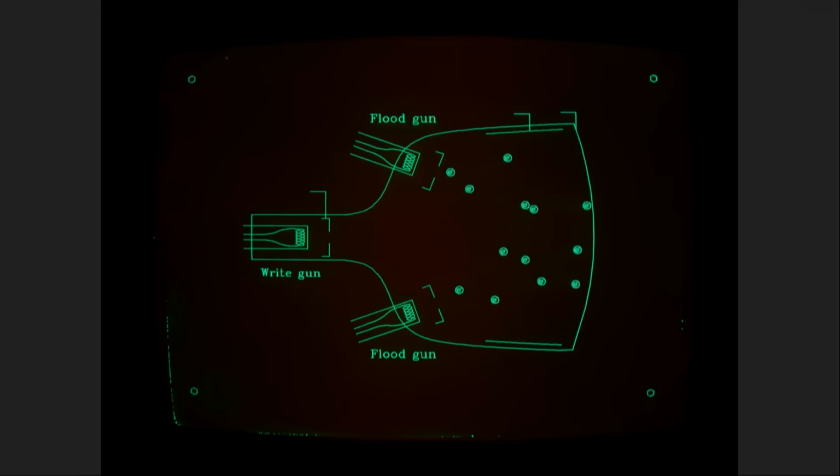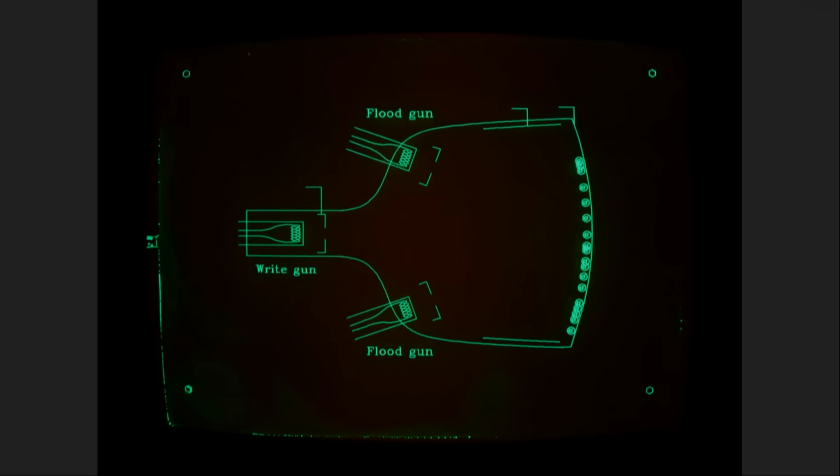Of course, however, real life is messy, and so sometimes the mixture of charges on the faceplate isn't perfectly balanced, like in the example shown on the last slide. If the faceplate target is rich in negative charges, then the flood gun electron will be repelled. It simply won't contact the screen at all. But this situation isn't sustainable. Eventually, the concentrated electrons will dissipate from the surface, raising its voltage back to something more reasonable. Conversely, if a patch of screen is slightly positive, then the flood guns will simply fill in these small gaps.